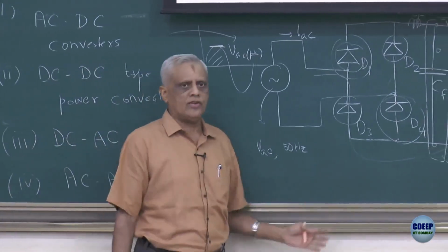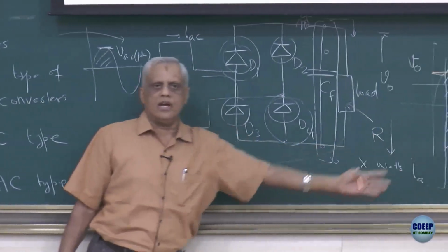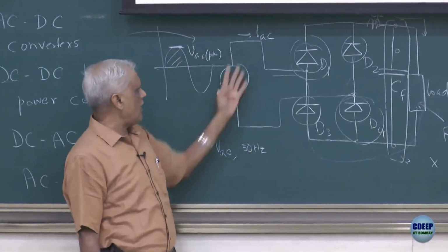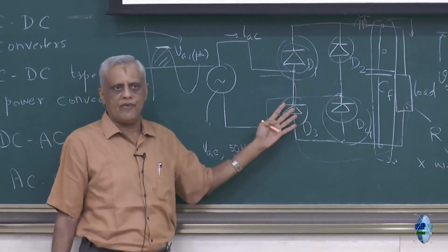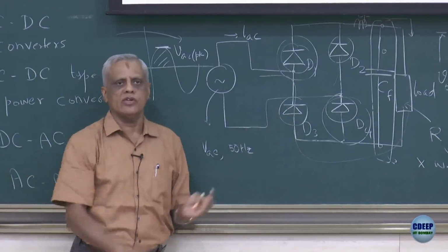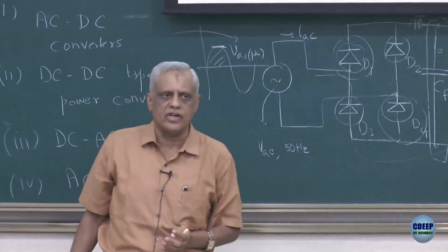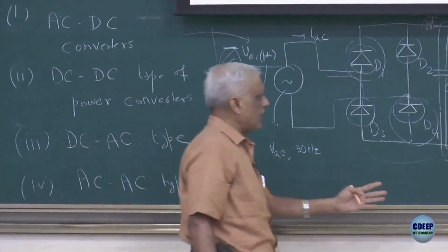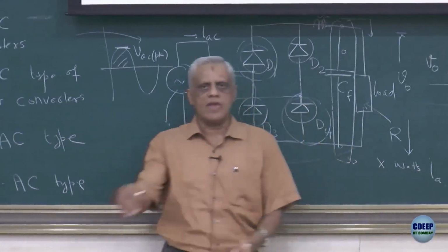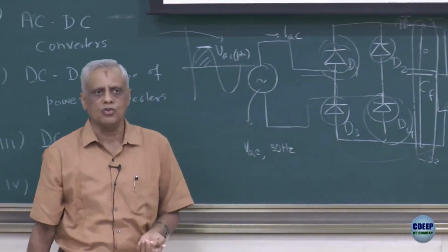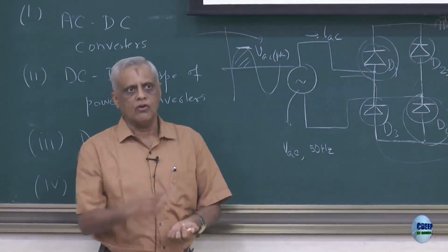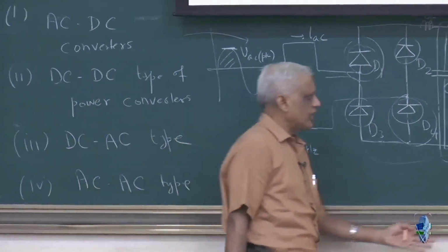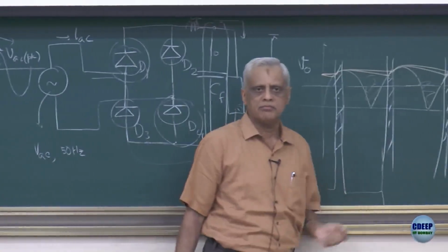because after all, where you have connected your load through this rectifier, there are many other consumers connected on the same power network, and this current, mind you, is coming from somewhere and it is affecting some other consumers also on the way, because there are voltage drops which will take place on the line, which will be very strange because of this kind of shape.